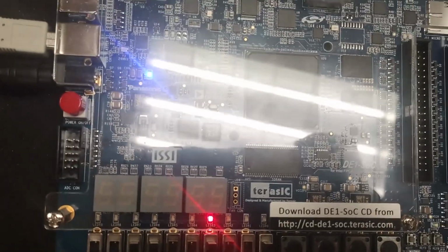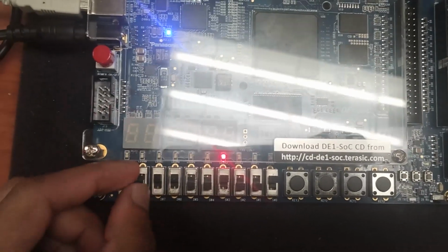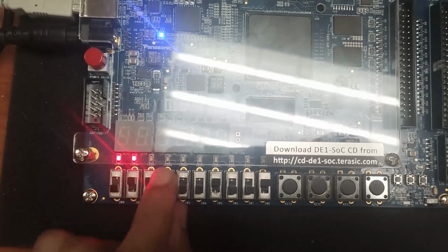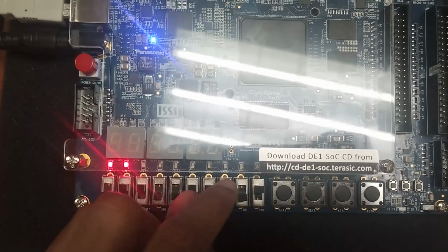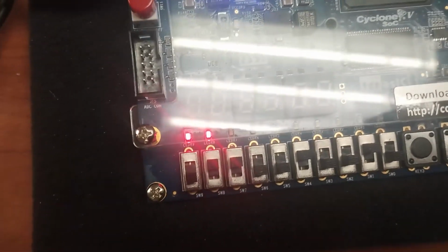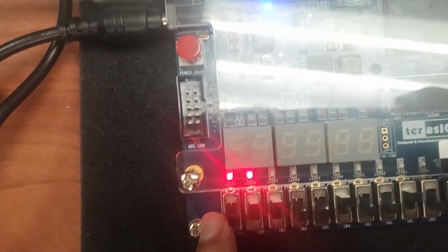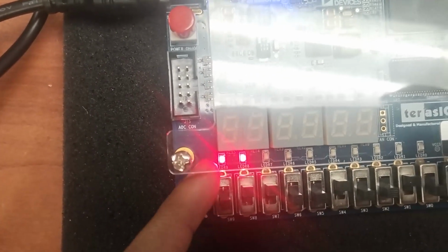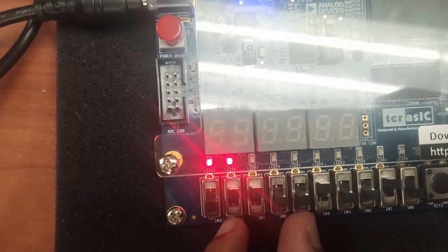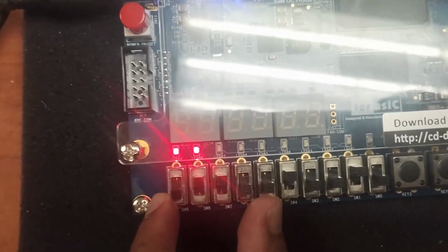Let me test for phase radian for pi. So let me make it 0 1 1 0 0 1 0 0 1 0. So this is the phase radian for pi. If you can see, for sine pi it is 0, and for cos, the MSB is 1, that means it's negative, and this is 1, so it's minus 1. So sine pi is 0 and cos pi is minus 1.